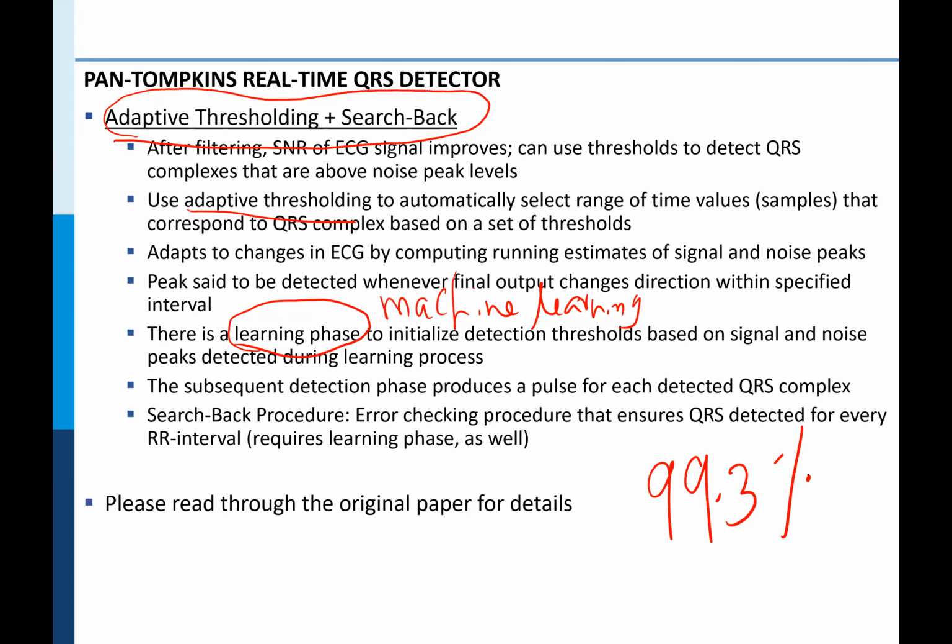So you could use a suitable bandpass filter to take out the P-wave first and go through the other subsequent steps we just saw for QRS complexes, the same methodology, use your own thresholding scheme, and you can get a reliable estimate of P-waves as well. Okay? So modifications and innovations are up to you.